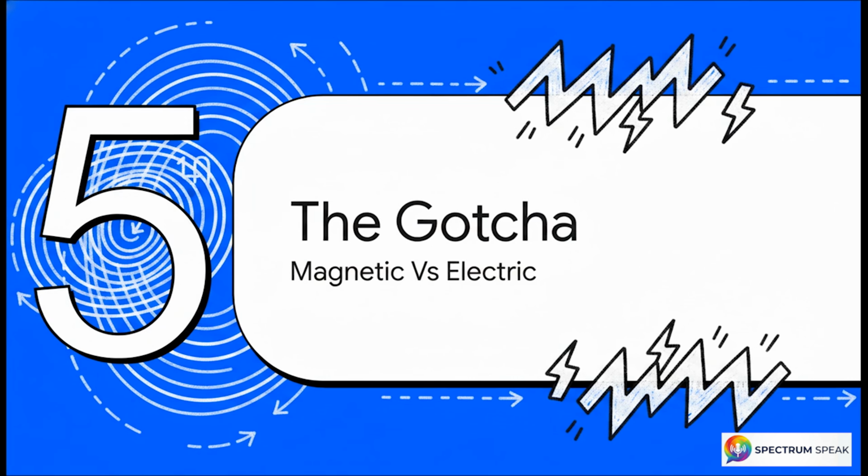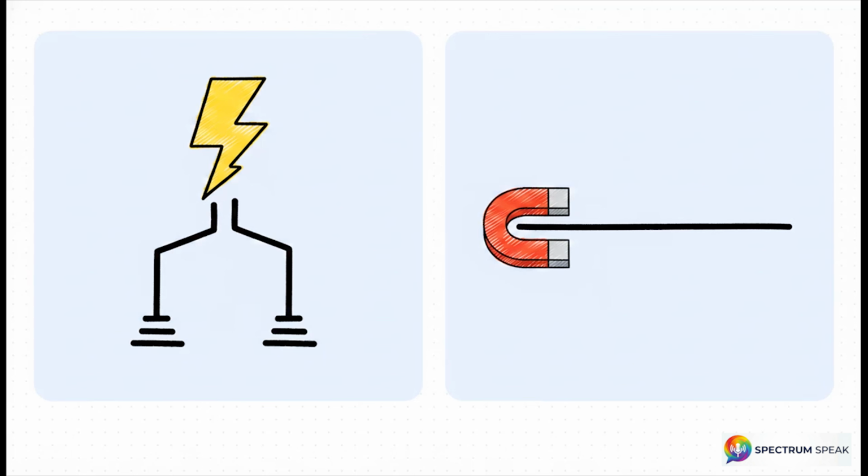All right, let's talk about section 5, the magnetic vs electric. Gotcha. Listen, you absolutely must diagnose which invisible force is attacking your circuit before you can even hope to fix it. This trips people up all the time. Here is the golden rule. Electric field coupling acts as a parallel current source connected between your receptor circuit and ground, but magnetic field coupling, which is what we've been deep diving into today, creates a noise voltage directly in series with the receptor conductor. Do not mix those up.